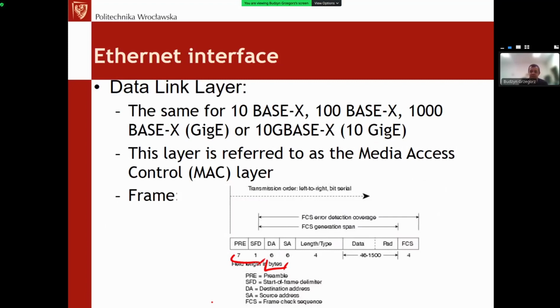And then comes the data field with the minimum length. Going back to CAN, a frame can be with no data. It's possible, it can be 0. Here, even if the data field length is 0, there is padding done. It makes sense, to be honest, because from one perspective we keep the minimum frame size, so we keep the network busy transferring the data.